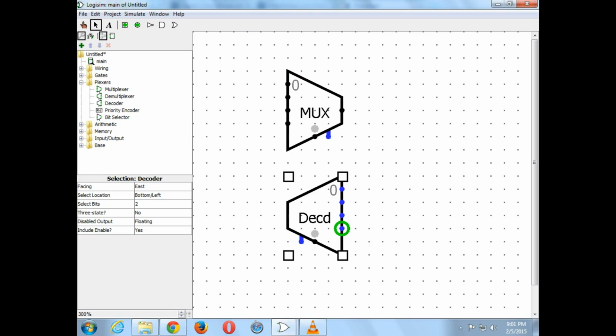Okay? But when you look at this one here, it is a 2-bit thing, because now we have 4 possible outputs. We need 2 bits to specify which one of the outputs to be quote unquote connected. But you don't see any input. In other words, if a decoder is really a reverse of a mux, where is the equivalent of this pin here? There's nothing here. And that's because it is implicitly connected to a 1.